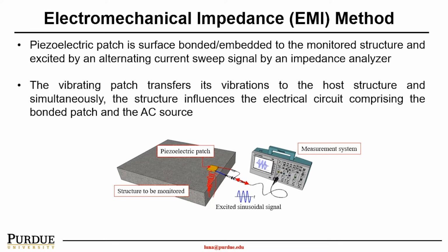The reason it is called electromechanical impedance is that we specifically look at mechanical impedance, which is the force over velocity of this particular wave, of course over time, the derivative of them. And so therefore we can understand the material's stiffness and the material's defects.